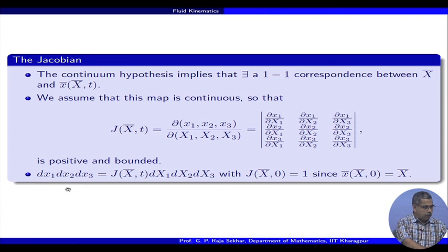Correspondingly, for any physical conditions, you take it and model, and then let us say you try to play with the corresponding coordinate systems, then you need some volume element. You see the volume element in Eulerian description is Jacobian times the volume element in the Lagrangian, and you can see this Jacobian at time t equal to 0 must agree with 1, because the position is agreeing with the reference. That means there is no coordinate transformation, right. So, what is the use of this? One can change the coordinate systems, Lagrangian to Eulerian and Eulerian to Lagrangian using inverse transformation. We will see the use of this very soon.